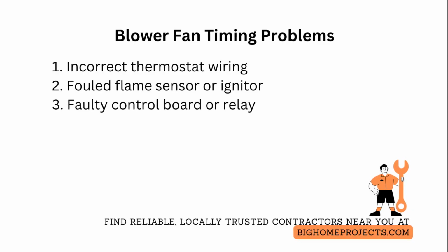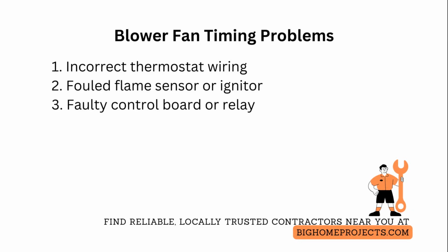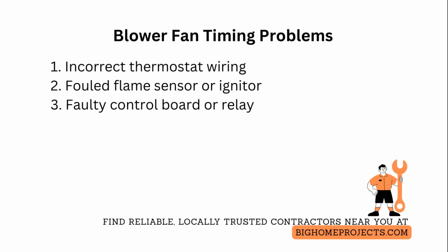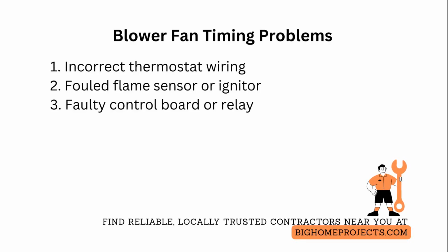Another frequent problem is a fouled flame sensor or failing igniter that leads to improper sequencing. Clean or replace those parts and test flame sense current to ensure stable detection.